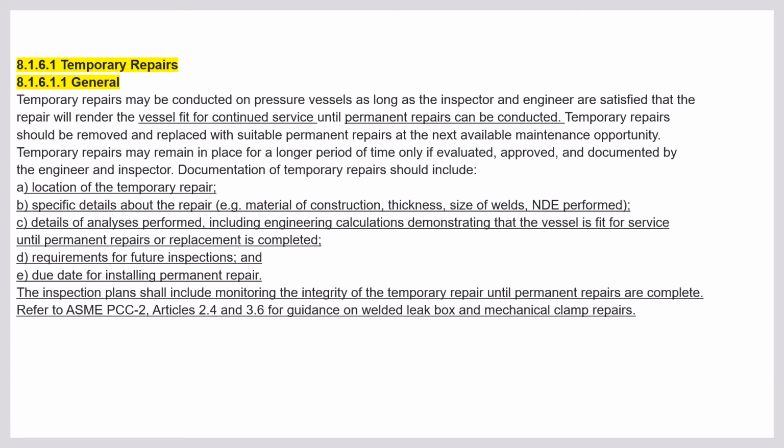Temporary repairs. Temporary repair may be conducted on pressure vessel as long as the inspector and engineer are satisfied that the repair will render the vessel fit for continued service until permanent repair can be conducted. Let's say a vessel is on service and you cannot do a permanent repair because the defect is critical and needs a lengthy process, or the defect needs a lot of time to repair. On that criteria, in that situation, you can do the temporary repairs. So temporary repairs, who will satisfy the requirement? The inspector and engineer to be satisfied.